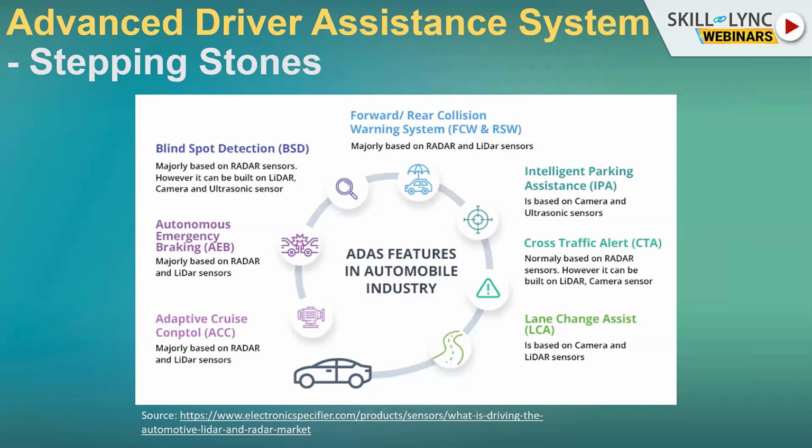This is a feature which works from a speed range of 0 to 60 kilometers per hour in traffic situations, only on highways. And here we can take the software from adaptive cruise control, because it's a traffic situation. We have cars in all three lanes, and we can always keep following the lead car. We also have the lane change assist, or another driver assistance feature, which is the lane keeping assist.